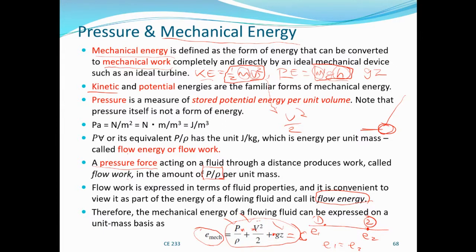Kinetic energy and potential energy are changing to flow energy, which has to do with the pressure. So the kinetic energy and the potential energy can make the pressure of the flowing fluid increase. This is because of the interchange of energy between potential, kinetic, and flow energy. Flow energy is a function of what is called the static pressure, which is P. P is the static pressure.